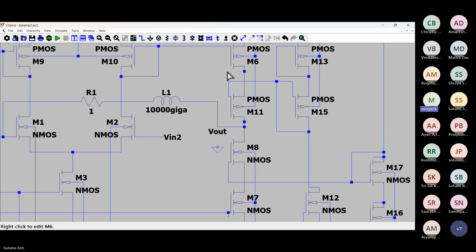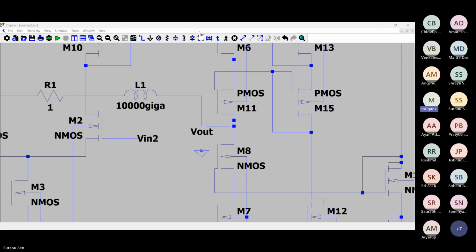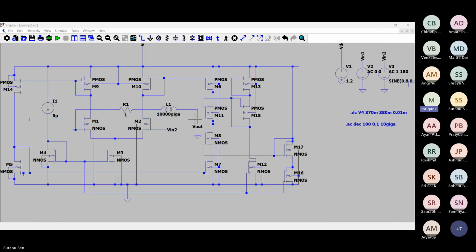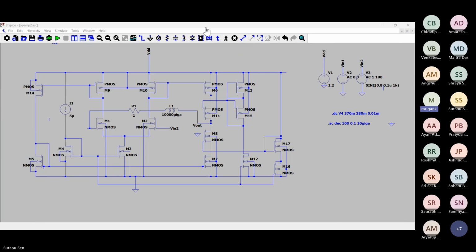We leave this for the time being. In this tool, we have to stick to that same approach where you find out the DC appropriately and then apply the signal. So right now, you are getting proper gain. So you are all set. And the only thing is, this kind of high gain we will not be requiring. And here 300K gain was coming, which is also a little surprising. I was not expecting this kind of gain. I was expecting maybe something of the order of 10K, something like 30K, 40K, but it is 300K. So we have some margin. We can reduce the gain also by a factor of 10x. Then also we will have good enough resolution.